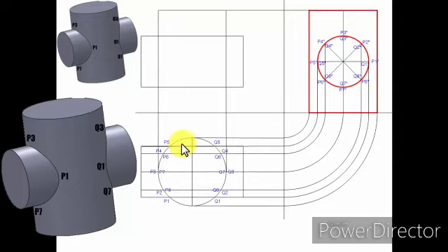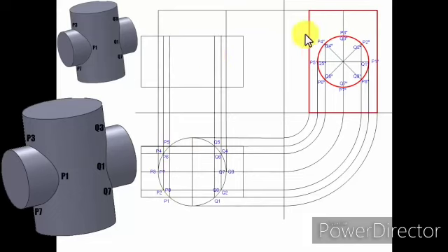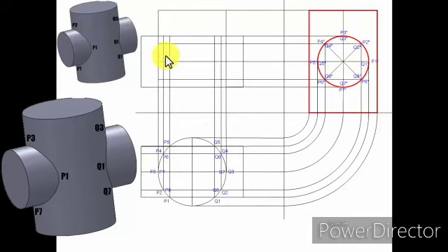How can that be done? Well, the process is pretty simple. You're going to have vertical lines from all these points over to this side, something like this, and all the horizontal lines from the side view over to this side. Fine. The intersection of these two lines is going to give you the points of penetration. Now suppose you want to locate this point P3. You're going to have two lines. One is going to be this one. This is the horizontal for P3, and this over here is the vertical for P3. Both of them are intersecting here. So this is going to be point P3 dash.